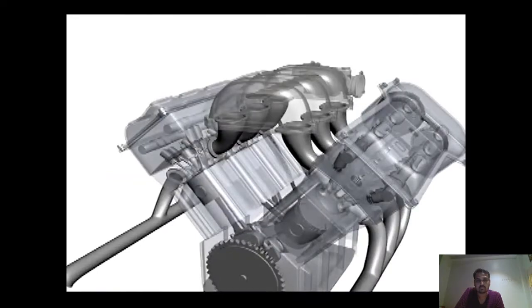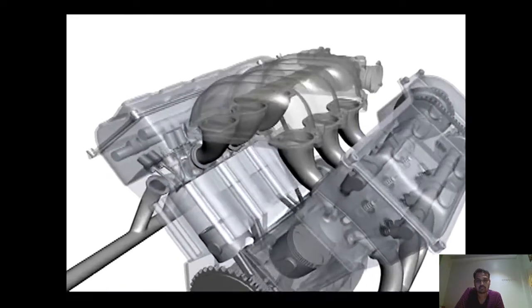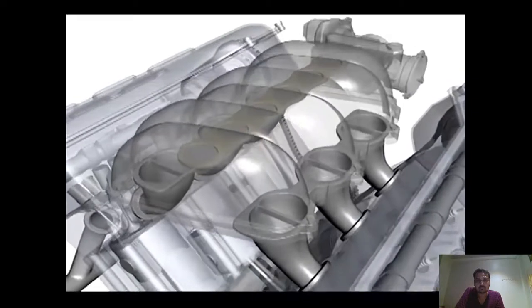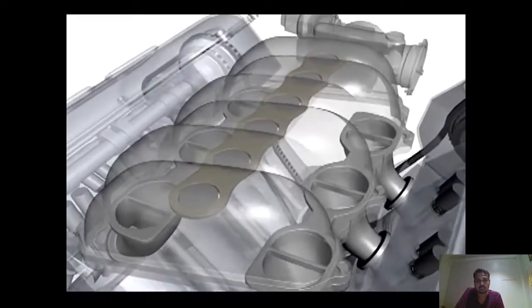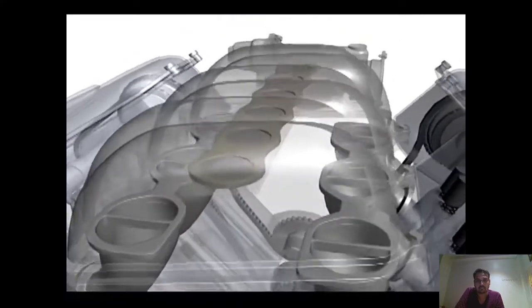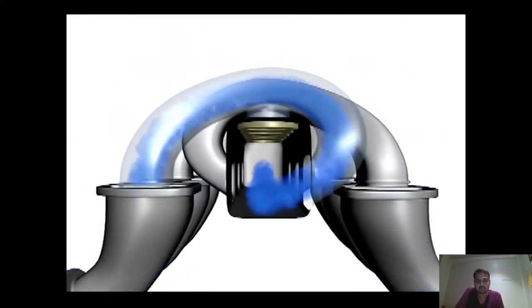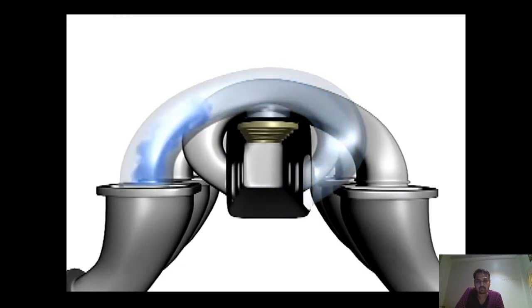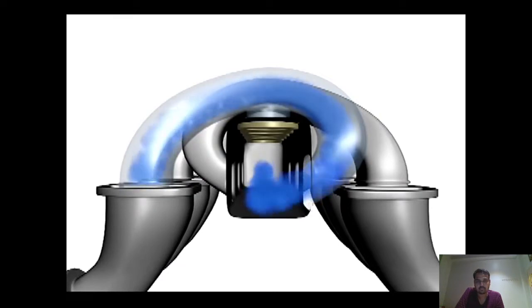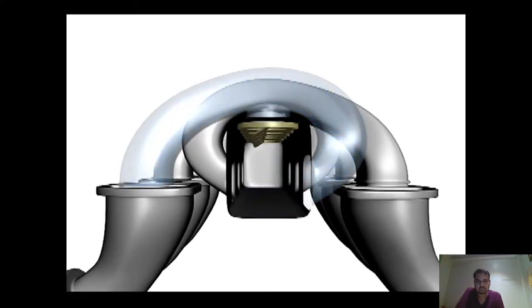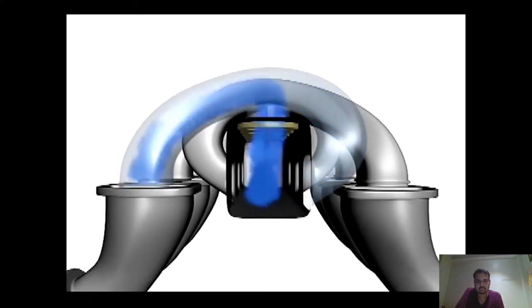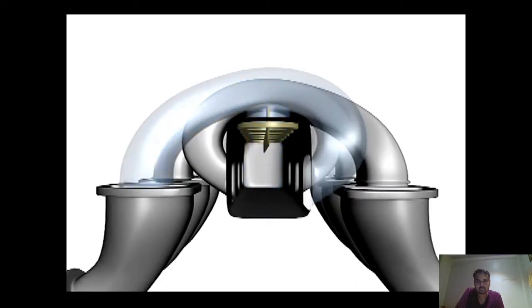An acoustic control induction system, or ACIS, automatically varies the length of the runners in the intake manifold to maximize the airflow into the engine and to provide more usable power throughout the entire RPM range. At low speeds, ACIS directs intake airflow through a long intake runner in order to produce ample low-end power and torque. Think of this as taking deep breaths while lifting a heavy object. At high engine speeds, ACIS directs the air through a short intake runner in order to generate more horsepower. Think of this as taking quick short breaths while running.